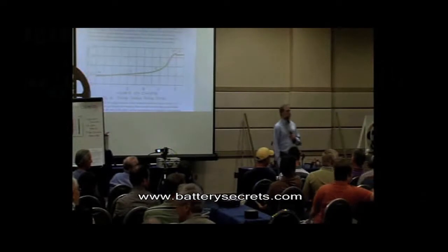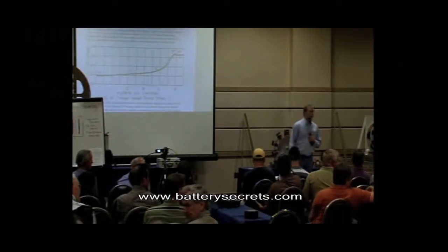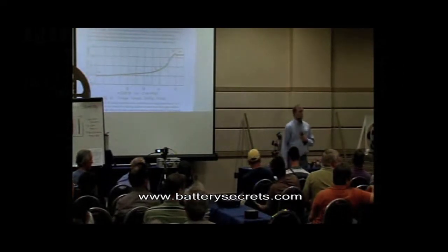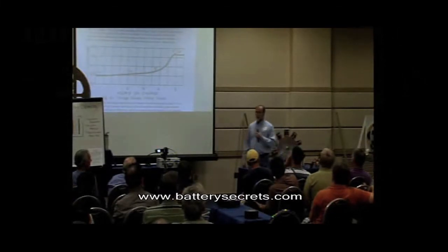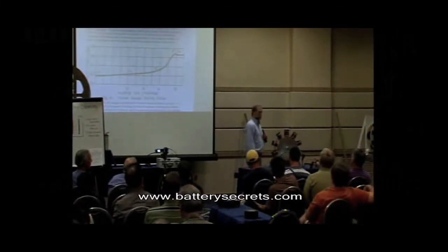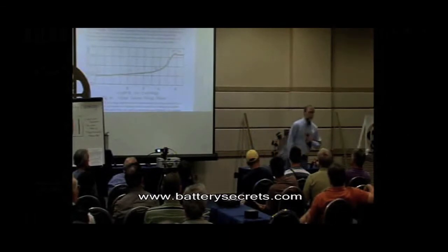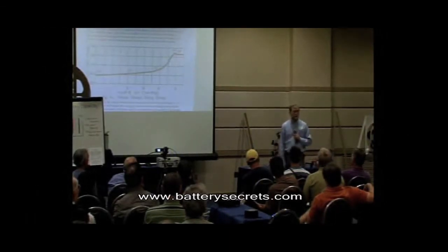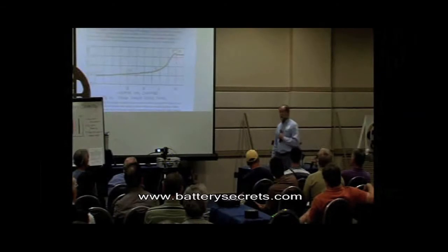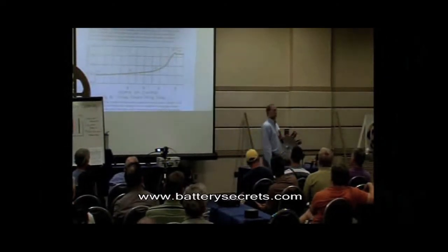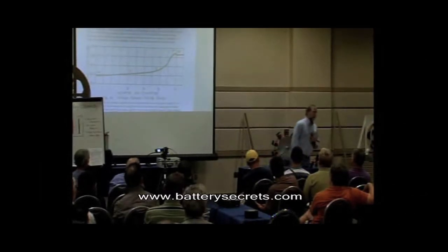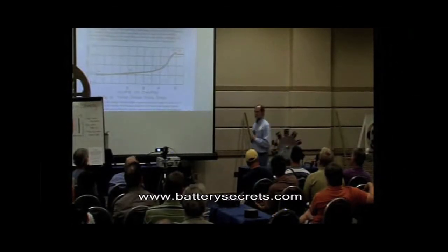What if you have a battery where somebody dumped the acid out? The question is, what happens if somebody who doesn't understand the chemistry of a battery dumps the old electrolyte out and just pours more acid in? This completely changes the balance of the ion structure in the battery. You may or may not ever be able to balance it out again. That's something that you should never, ever do.